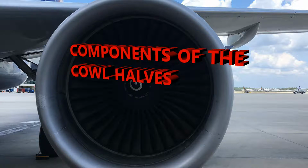There's also, I mentioned, the translating sleeve. Those are the ones with the blocker doors, because they block the airflow. When that happens, it's creating the energy because it's blocking that air and diverting it. There are the actuator access panels located on the outer surface of the translating sleeve, and that's going to allow access to the actuator attachments to the translating sleeve. Just be aware of that. Of course, there are hold open rods as well with the thrust reverser cowls.